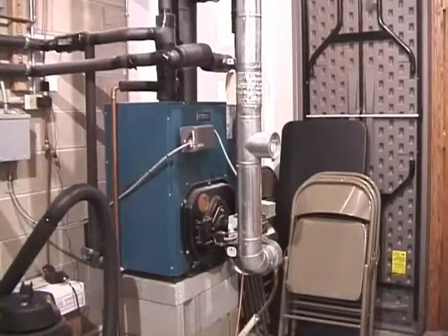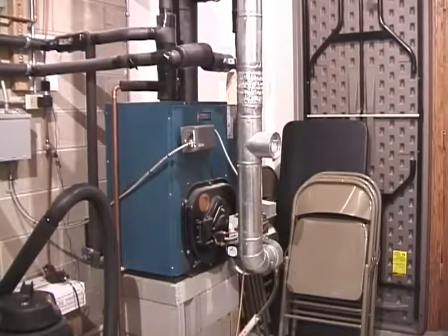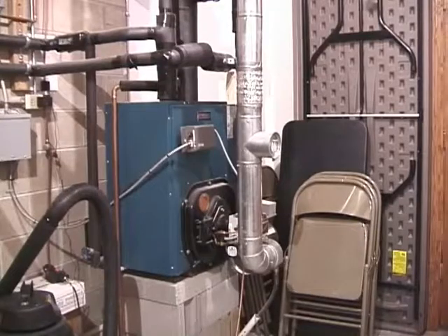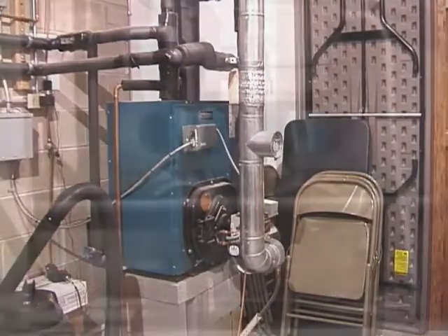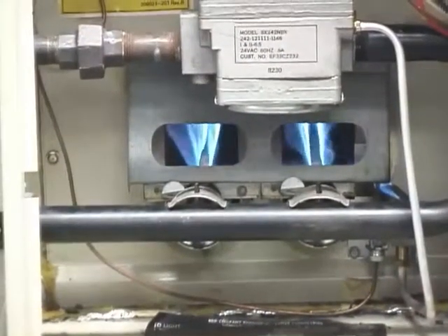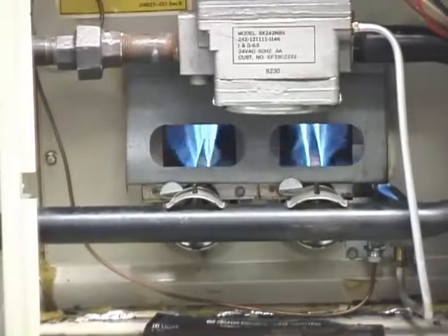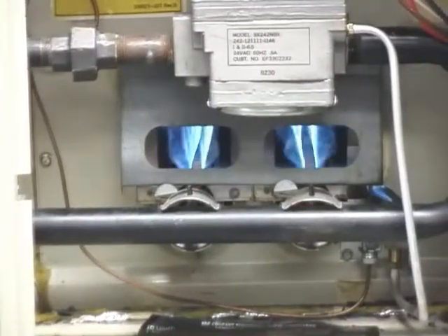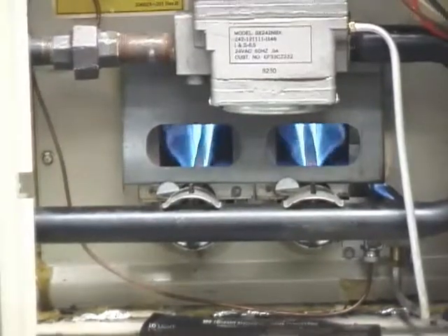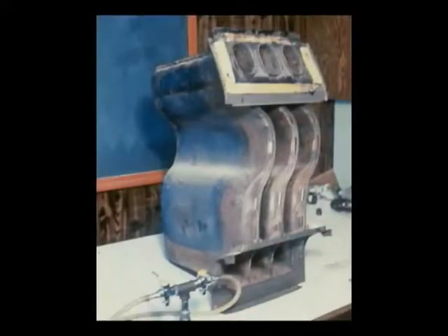Partly because of higher flue gas temperatures, most oil-fired appliances have stronger draft than gas-fired appliances. An under-fired unit, possibly due to an improper orifice or gas pressure, may have low vent temperature and weak draft. Excessive airflow over the heat exchanger can also overcool the combustion gases and weaken the draft.